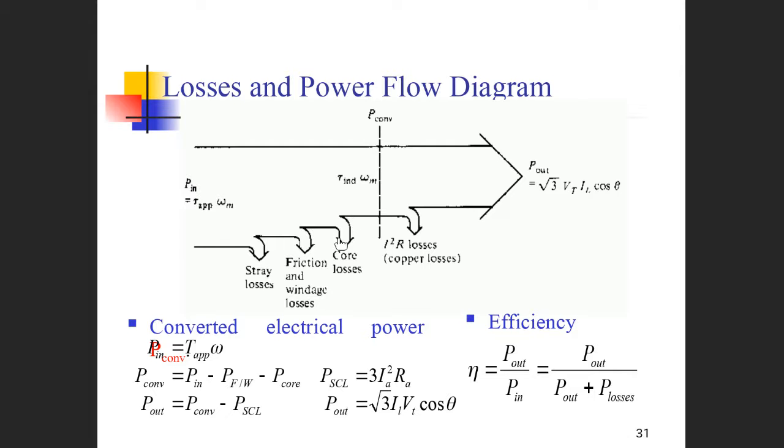The third one, of course, is the core losses. Once there is generated voltage and currents, there will be core losses. When there is generated voltage across the coils, there is a magnetic field inside the coils. If the core material itself is conductive, there are small currents there. So eddy currents and hysteresis losses occur inside the core materials; that is the core losses. The energy left is the pure energy for the induction. So here, the pure induction is the voltage generated.